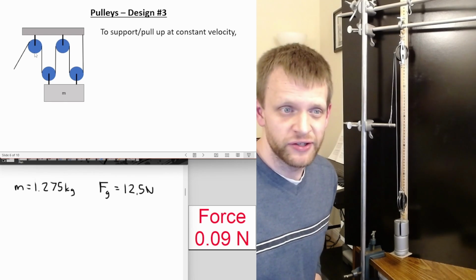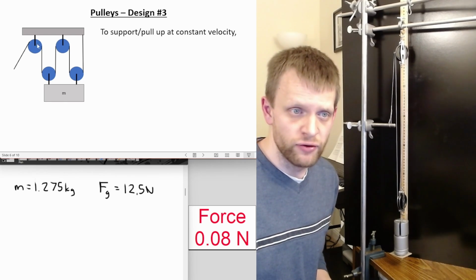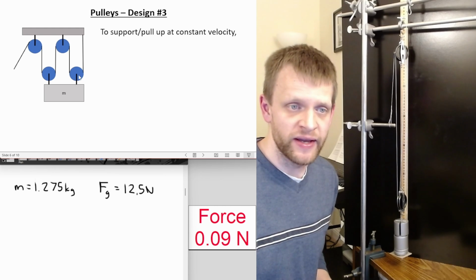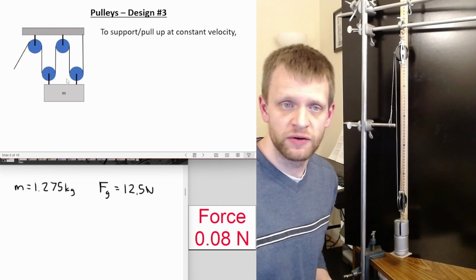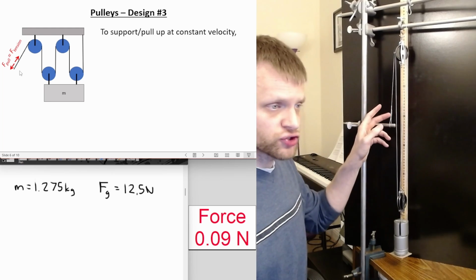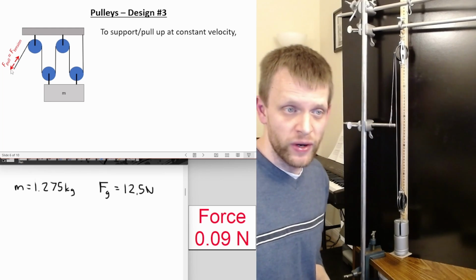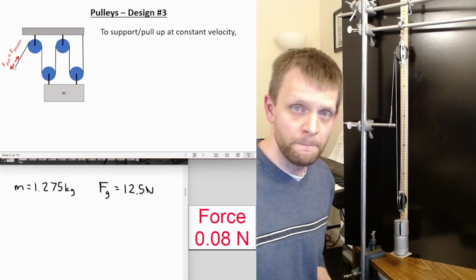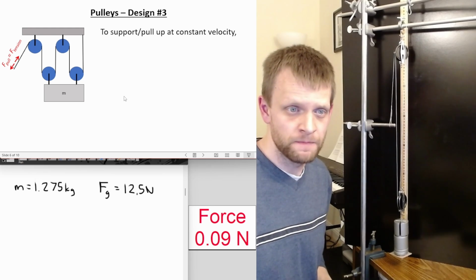This one, we've actually got 4 pulleys, and we wrap the string around these pulleys in this way and hang the mass from both of these bottom 2 pulleys. So the side of the string that I'm actually pulling on, again, whatever force I pull with, that will match the tension in the strings.